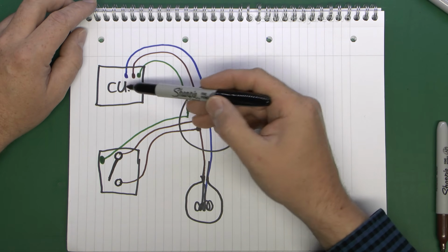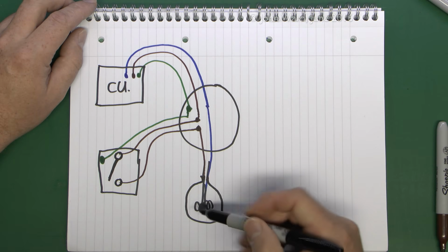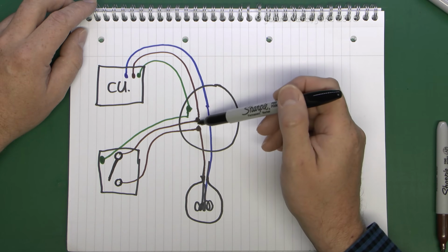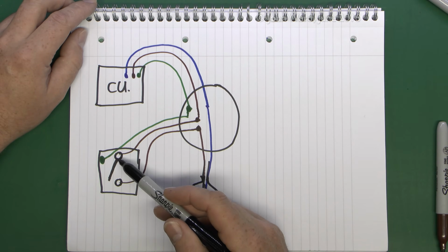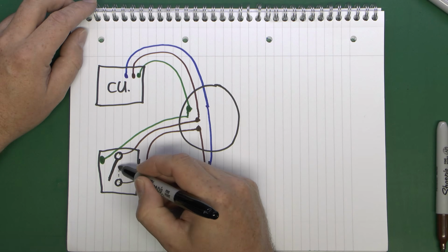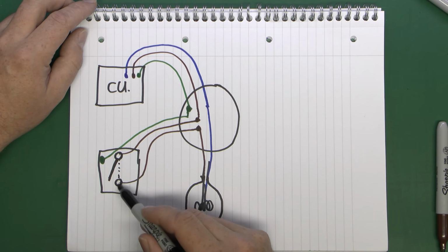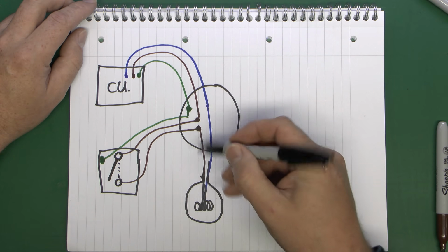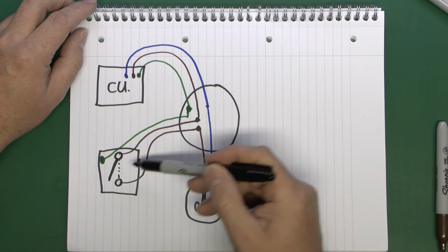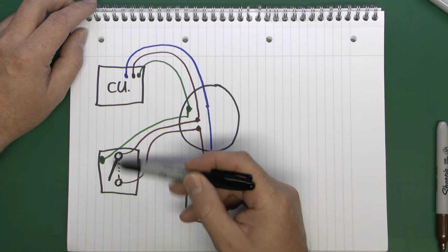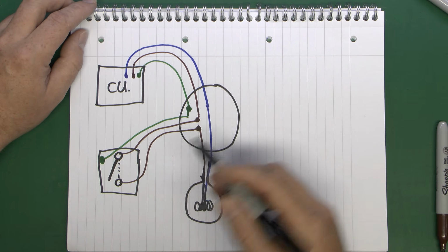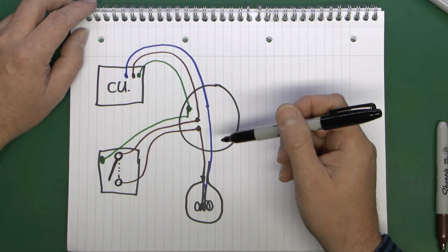So now what we have then is the neutral here is actually connected permanently right through to the light bulb there, but the line coming in with the power actually comes through, goes to the ceiling rose first, but then is diverted over to the light switch over here. And then if the light switches happen to be in the on position, so these two are connected together, then power can continue through there and return via the other wire here, go through into the lamp, and of course that's when it will switch on. And of course when you opened it, then there's no connection here, so although this part here is live, this side is not, and the light no longer works. And at its simplest level, this is essentially how all lights are installed and wired.